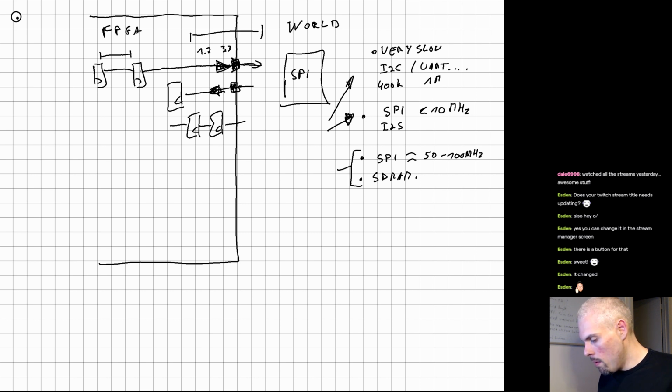And here you do definitely have to worry about the timing, but you can do it in a static way, which means it's essentially an analysis by the tool or by yourself, pen on paper, drawing the different timing and ensuring by design that the IO timing is going to be met and that everything is going to work fine.